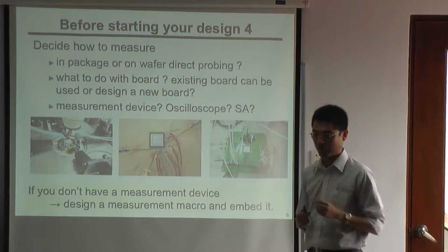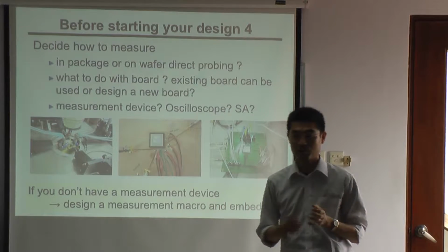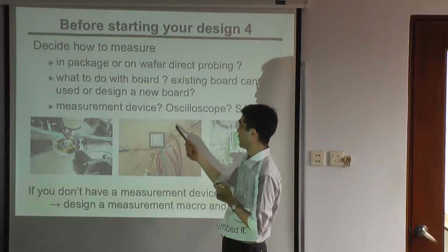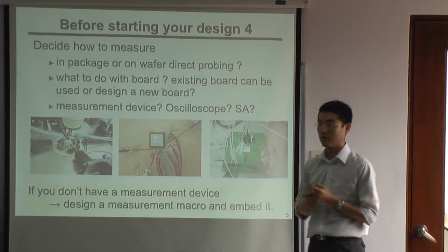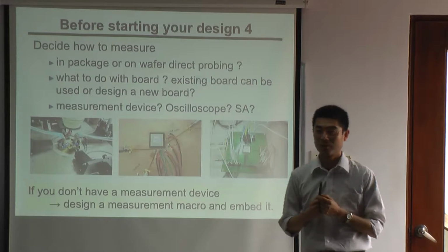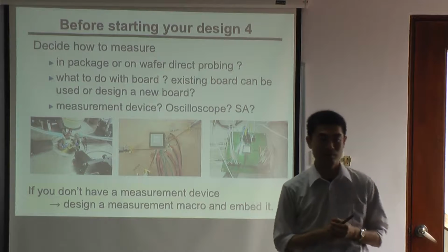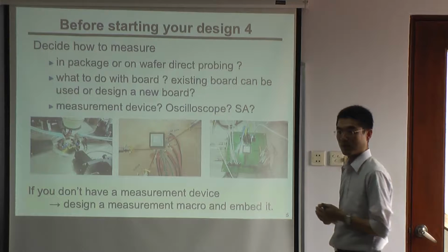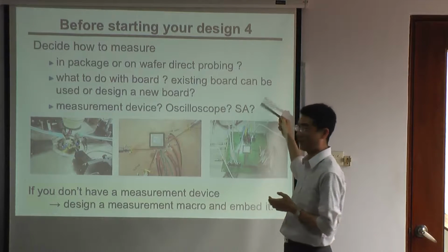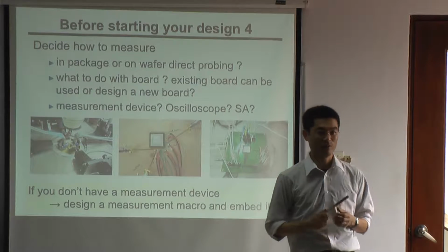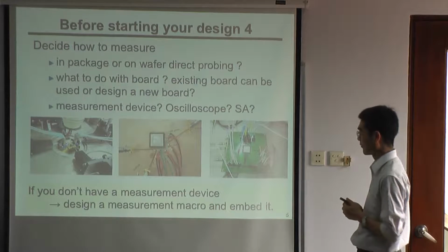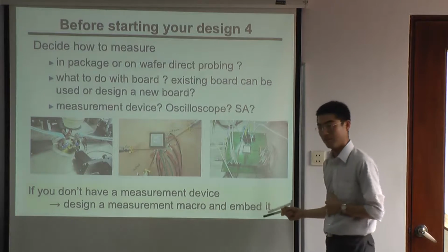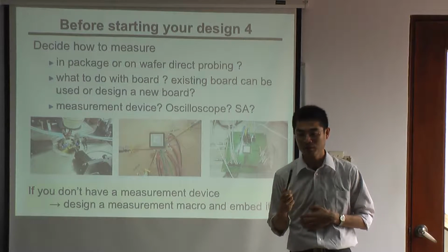And also we want to make sure what kind of measurement device we will use. We will measure the chip by oscilloscope, or spectrum analyzer, or real-time oscilloscope, or sampling oscilloscope, or using network analyzer. We have to consider how to measure before starting your design.